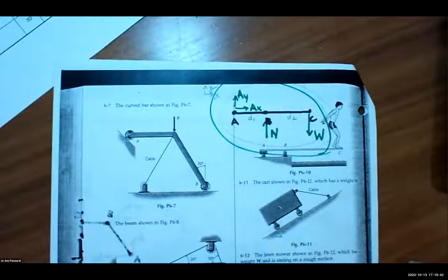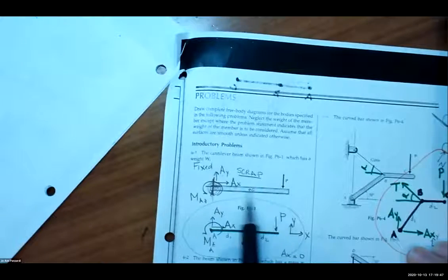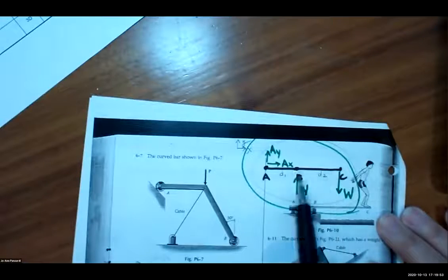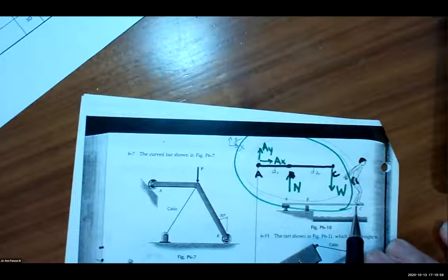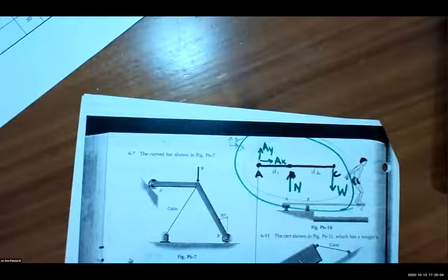Joanne? Yes. I thought we were only taking the weight when there's a little g. Yeah, but they're talking about the weight of the body. So there's a little g here because they want you to include the weight of the beam. Here, the diving board is negligible, so you don't use the weight of that, but you still have to account for the external load of the weight of the person on it. Good question. The reason why in statics many times we ignore the weight is because the weight is so light in comparison to other things.